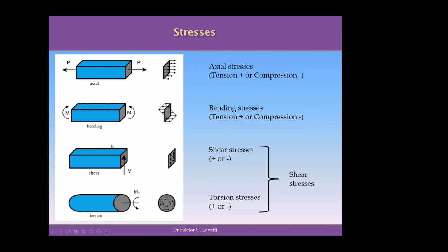And remember that usually it's produced in combination when you bend a beam. And the distribution of the stresses is like this, so there is not a volume of the stresses, because the shear stresses act on the cross section directly in the same direction, differently to the axial stresses and bending stresses that act perpendicularly to the cross section. And there is another source of shear stresses, that is the torsion, which is a 3-dimensional effect in a structure, so you cannot study this in 2 dimensions.